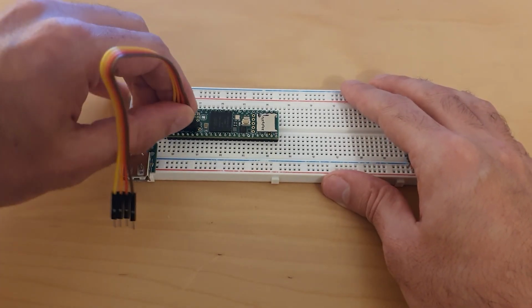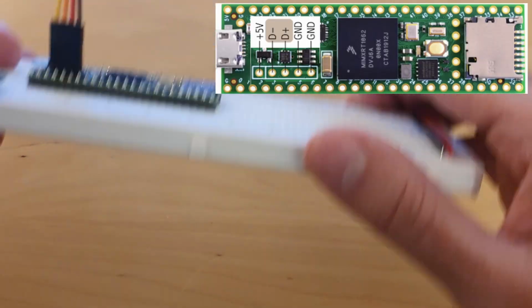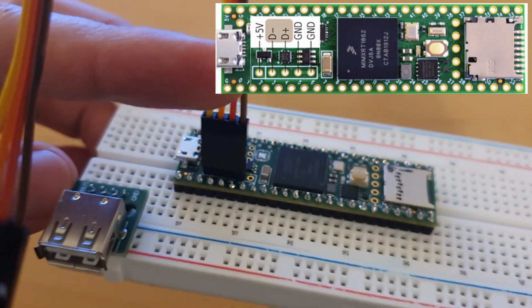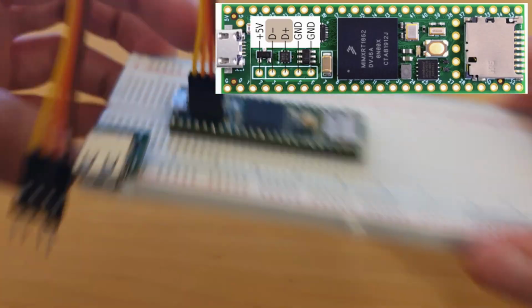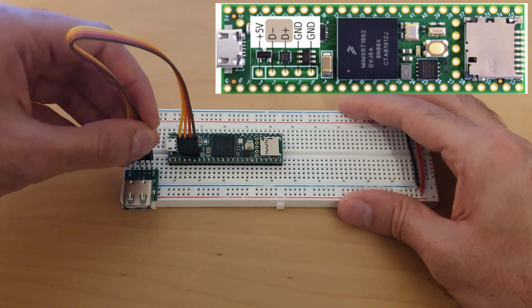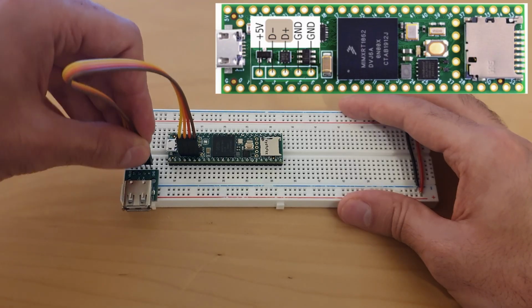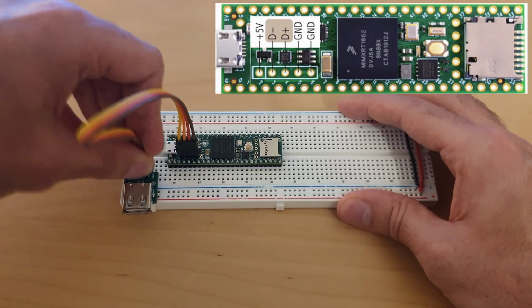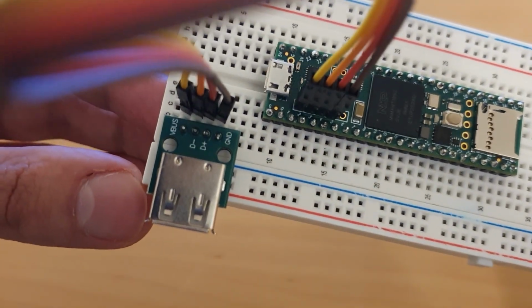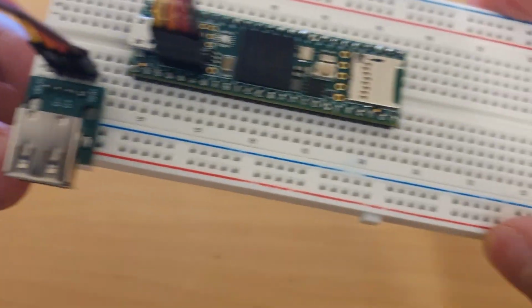So we've got this side plugged in, you can see there. Whoop. So the yellow's on the left here and the brown is on the right, so we need to make sure we maintain that orientation so that the ground will go to the ground and the 5 volt will go to the 5 volt. So you can check the website for the pinout on that and just verify everything's correct. Yep, you've got the brown on this side, the brown on that side.